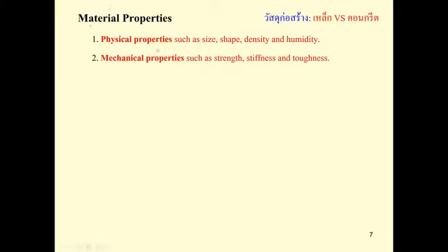Usually the physical property, when you buy the steel, you got to measure the size. For example, if you buy 25mm steel and then the company sends you that steel, you got to go and check whether some of them are at the correct size or not. If not, just reject it, return it to the company. Don't waste the money on that.